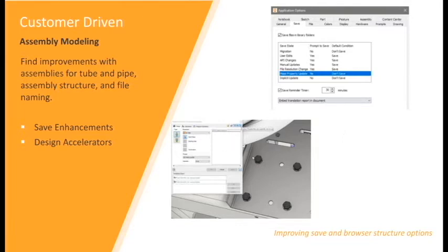Another new feature with 2021, for those of you that use the bolted connection feature: in 2020 and older, Inventor would always bring in the bolted connection as a subassembly, and that subassembly is set as phantom. Then in your parts list, you would see the components that make up that subassembly. Where that selection arrow is, you can now have Inventor bring in your bolted connection as just individual components within your model tree. You would not see the subassembly, just the components. So you have an option to do either one: do you want to see that subassembly in your model tree, or only the components?